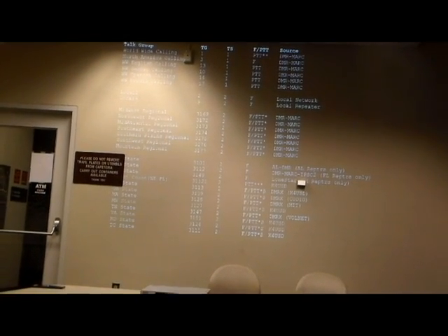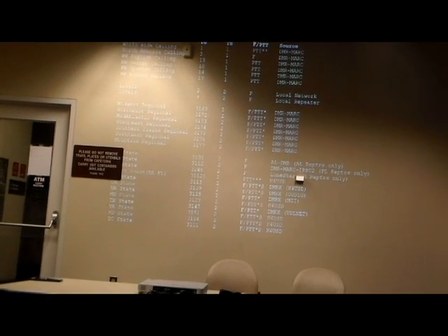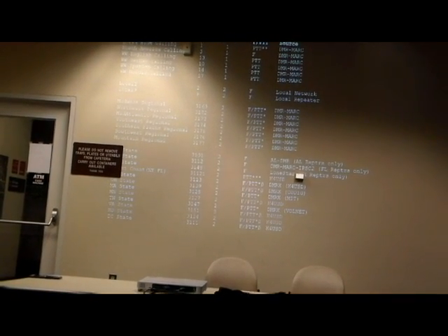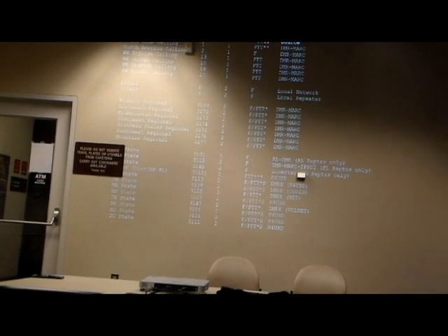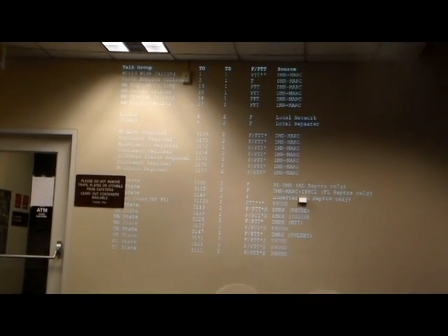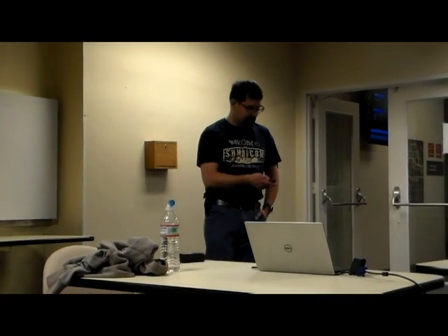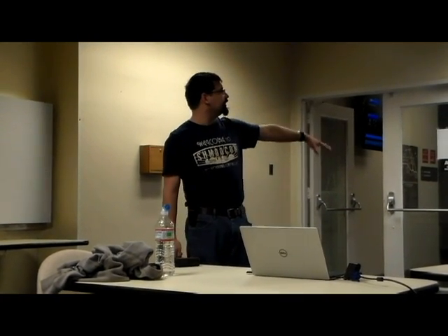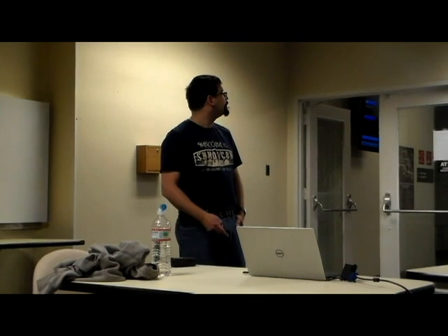The time slot is like a channel, right? Well, kind of, it's a sub-channel, like when I was talking before. Yeah, and it's generally done by the radio configuration. And generally, you're only listening to one time slot at a time, right? That's what the radio is duty cycling to save you power. So I don't know of any system that allows you to listen to both time slots simultaneously. I'm sure they're out there, but they aren't in wide use, and I definitely can't afford them. So just kind of an example of how these are set up.